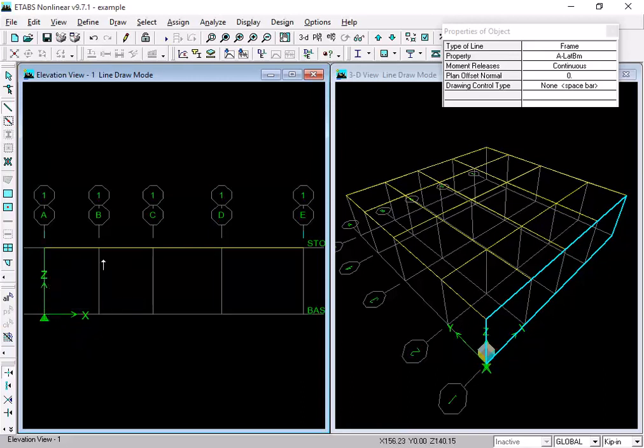Right click, and you see that when I click at the bottom, the software itself installs a hinge support. If you do this in SAP, then I think it won't install this hinge support. Why? Because this software is developed for buildings, and it understands that this vertical member is a column.